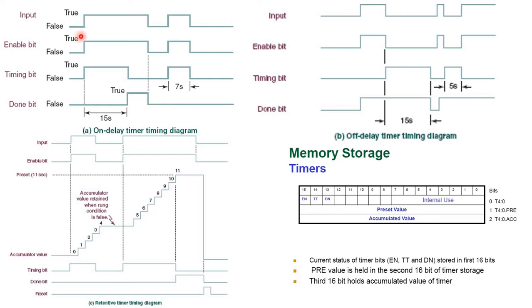Let's say for the T-on timer, it is pretty straightforward. You have an input, maybe a simple maintain contact, and you want to use this input to turn on a device after a certain delay period. So you turn on this maintain contact by changing the status from false to true.